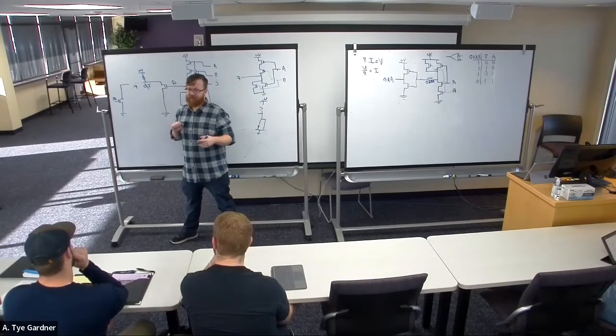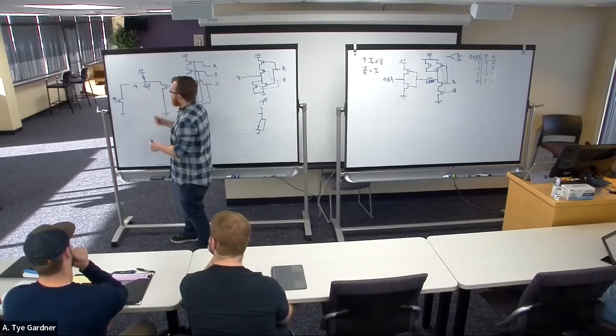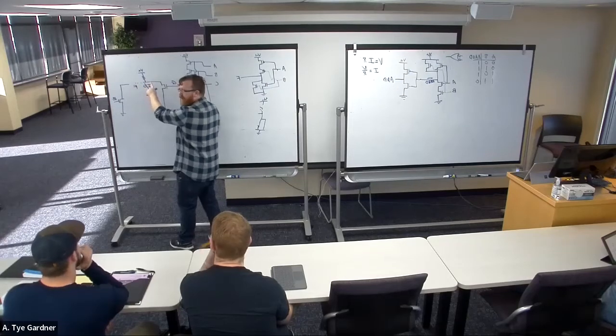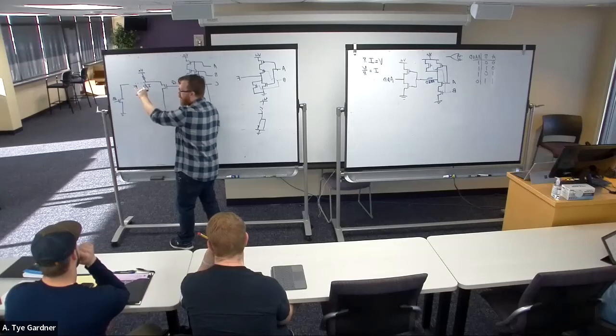That's because it's a pull up network. Yeah, because a pull up resistor is servicing both of them, and you're never going to have this because this isn't a CMOS device. It can handle that current flowing through it and be okay.